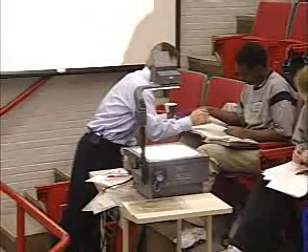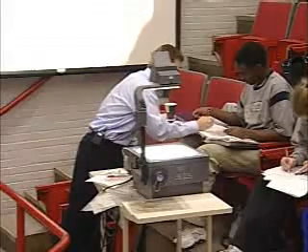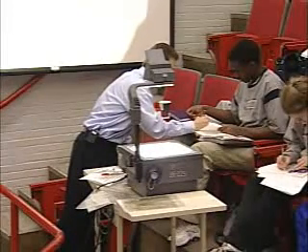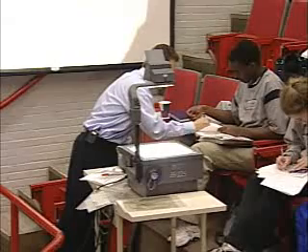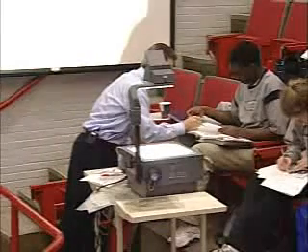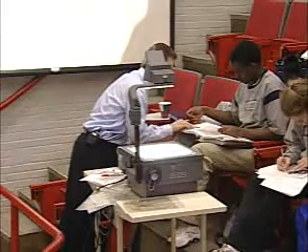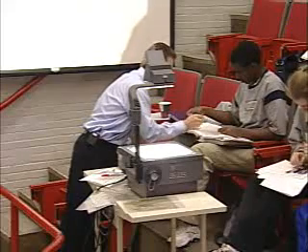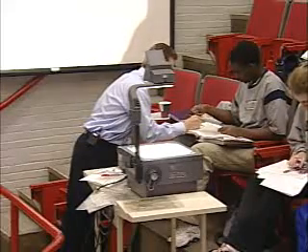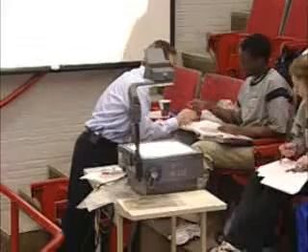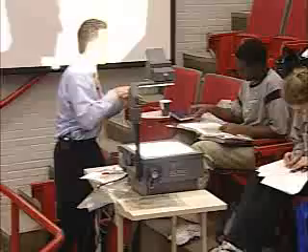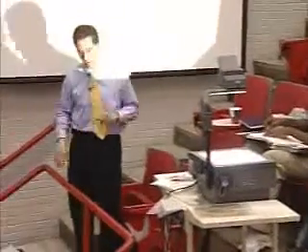Yeah, the triangle. So here, for example, you could say, well, the flow coming out of this stationary blade row looks like this, right? Because it's got to have this length, and it's got to have this angle. And then subtract off that same length. And then this would be sort of the relative frame, 1. So this is what I mean by draw it right on top of it like that, all right?